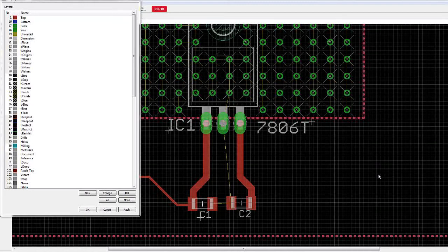The measures layer contains measurements on the board. If you use your measurement tool in Eagle and you want to save it there, you can put it on this layer and it will not go out to the Gerber files, or it won't go to the manufacturer. It will not be printed on the board. The document layer is just a layer you put your general documentation on, like copyright notices, things of that nature, on the board file. These are not printed to the board.